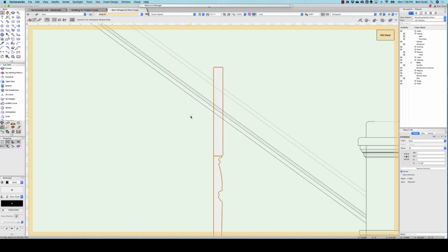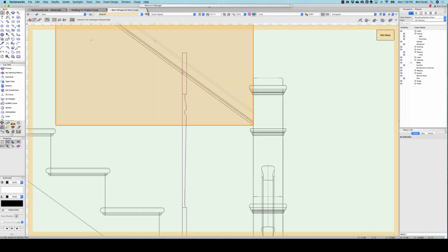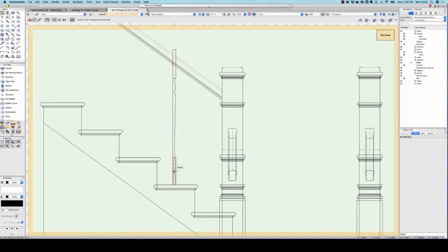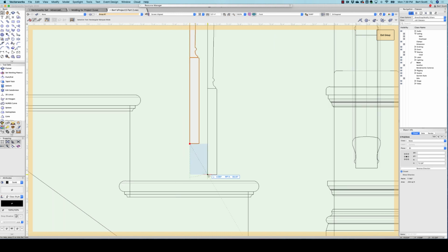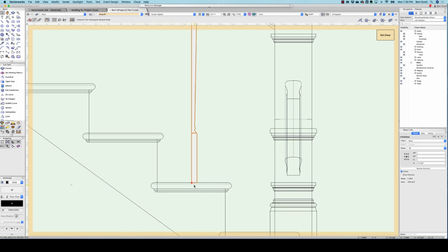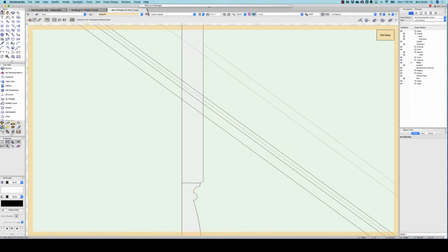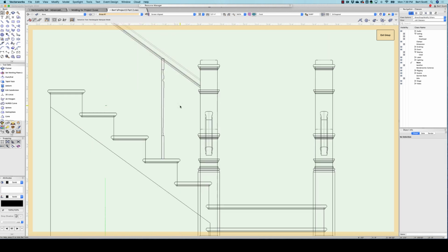Actually, we can go ahead and chop this. We make sure this is in the center of the step first. So we're going to align the center, or the left side of this with the center of the step, and then we can cut off. I'm going to go a little higher, since we're going to have to do a solid subtraction to get the angle anyway. So modify clip surface, delete, delete.